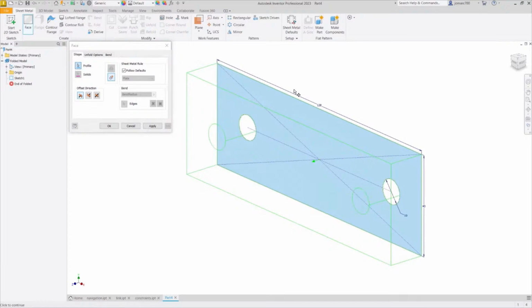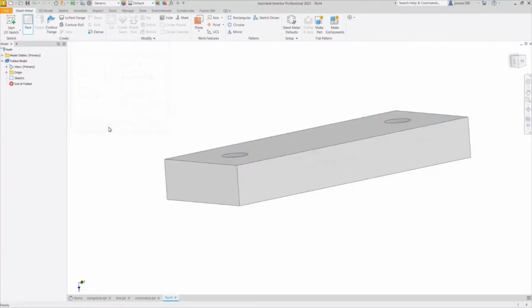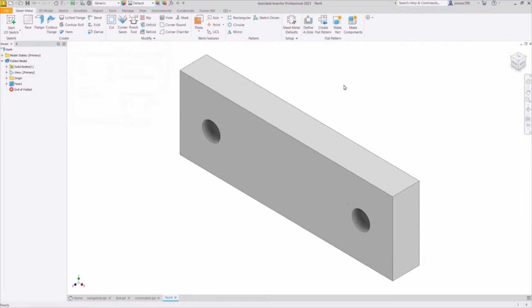And of course, one of the best practices, making things at the center or middle. I'm going to select both sides for offset direction. Selecting OK. And let me hit M for measure. Selecting this edge and confirmed. It has a thickness of 15 millimeters. Hitting escape. Plate part completed.